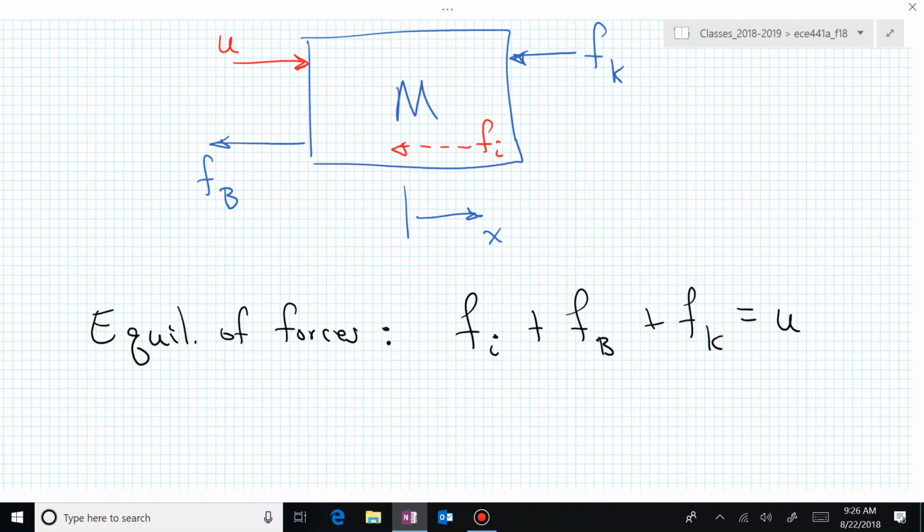So now, instead of saying sum of forces equal mass times acceleration, we just say sum of forces, and we're already accommodating for the mass times acceleration. That is our inertial force. The inertial force is simply the mass times the acceleration of that object. So the inertial force is just ma. It's m x double prime. That's the inertial force.